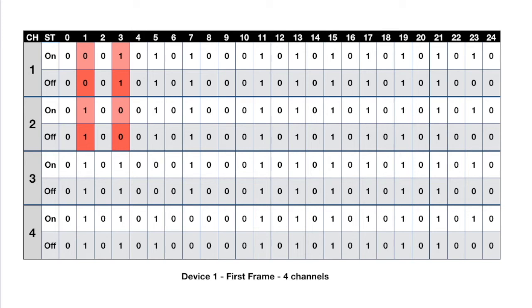So we see that channel 1 is when there are bits zeros in the 1 position, whereas channel 2 bits are in the 3 position, and then channel 3 bits are in the 5 positions, and then finally channel 4, the 0 bits is at the 7 position. So interestingly enough, we realize that what we thought was a preamble was actually the choice of the channel that has been transmitted in the clear, just like that.